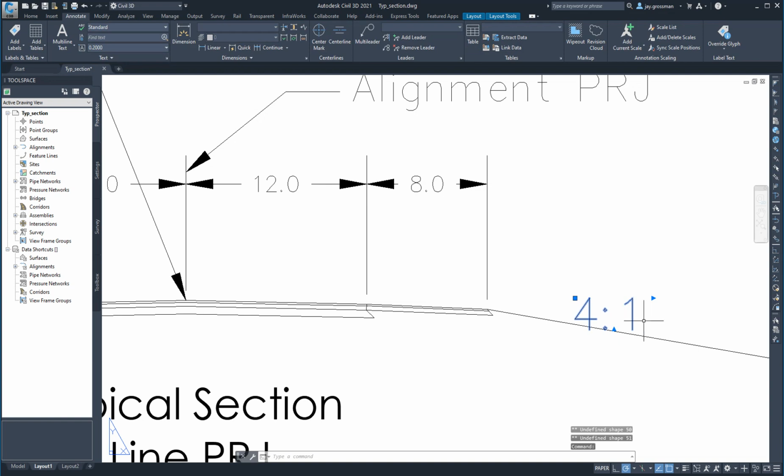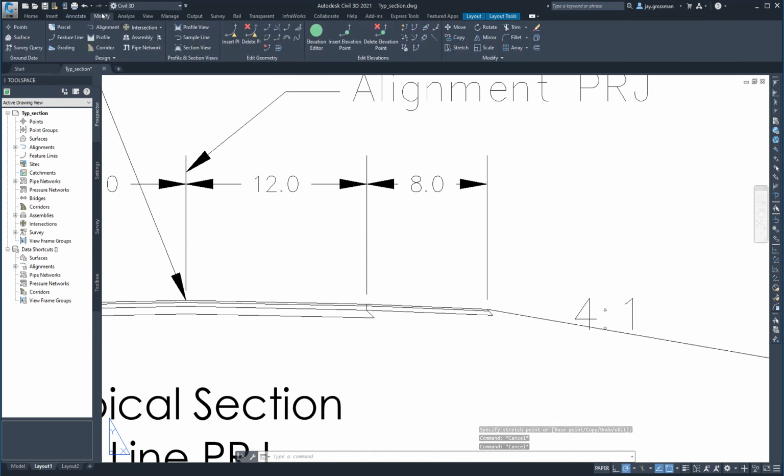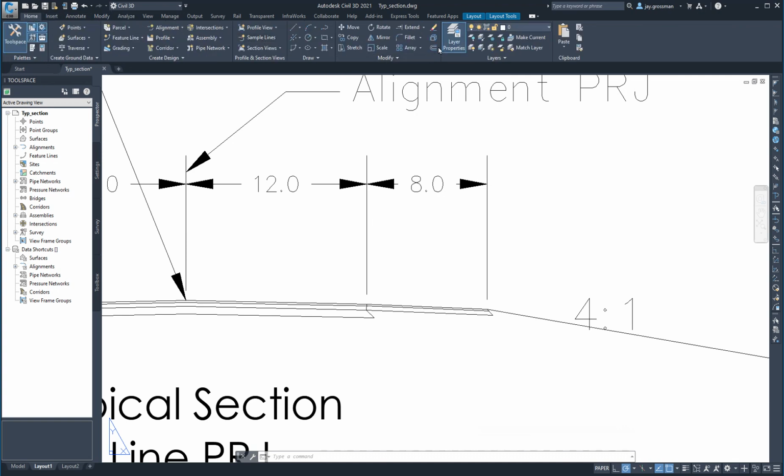I can click that. I don't think that rotates it. Nope, that doesn't rotate it. I can use modify, and I can, well, come on. Home, under the modify commands. Under here should be a rotate somewhere. There it is. There's rotate. What am I rotating? I'm rotating that. Base point, and I can drive this thing around. That looks like it's lined up.